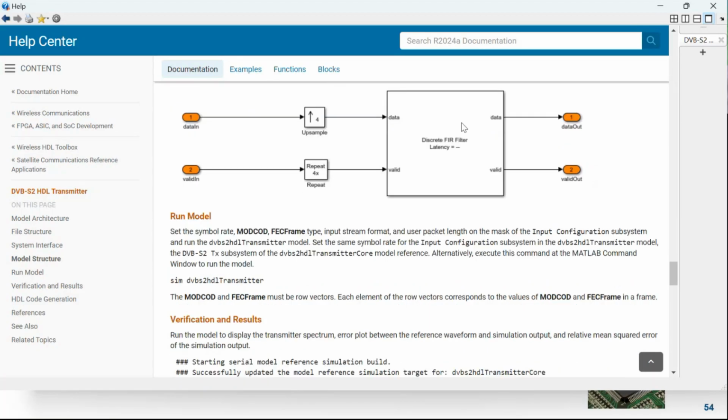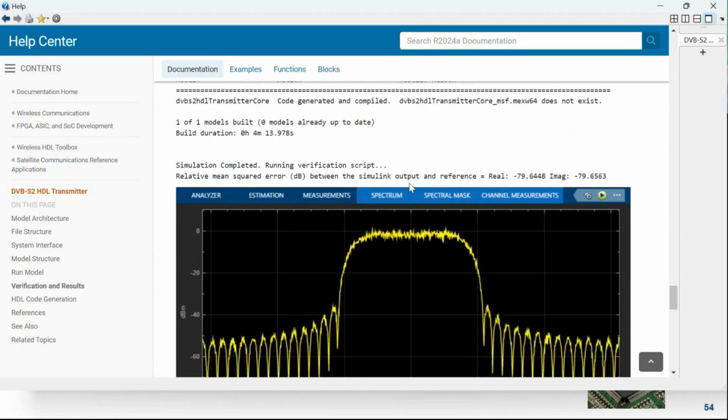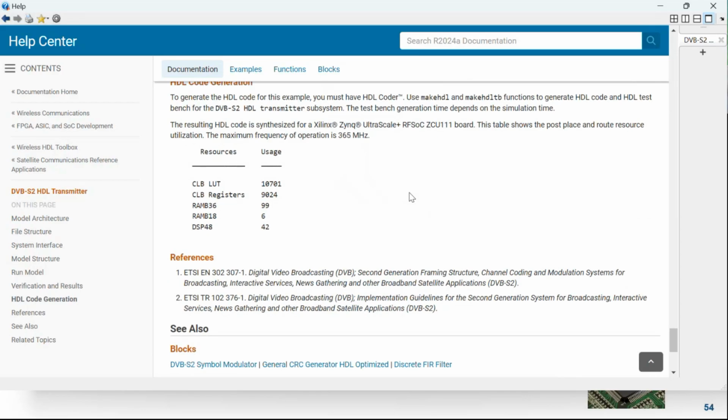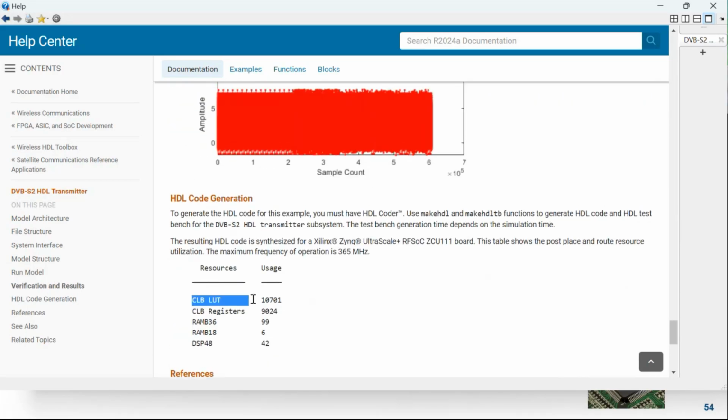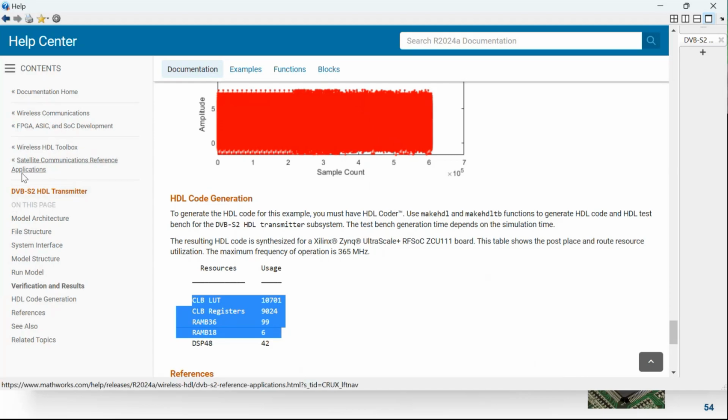But the beauty of it is all these blocks, they generate code that you can read. It's not a black box that is, you know, impossible to read. It's code that is documented. We've got some estimation of the resources for each of these blocks, so you can tell, okay, is it going to fit? Is there a chance it's going to fit on my target or not? We can generate the HDL code and the C code, and there is a communication in between. So yeah, this is something that once you've got a baseline can really help you save a lot of time, because you focus on the model, you focus on the algorithm, you focus on the design, and then the code generation is automated.